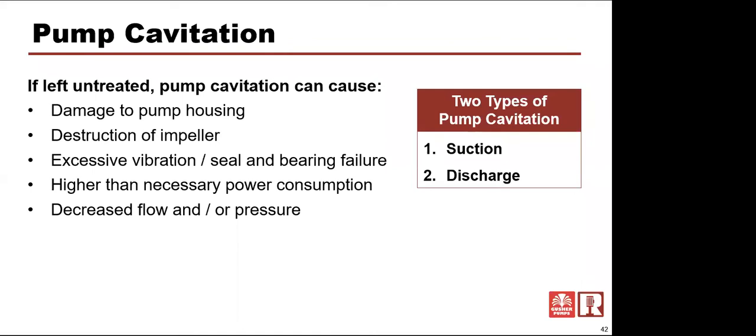It will cause premature seal and bearing failure because of all of that vibration. Again, when we get shaft movement, when we get vibration on a rotating piece of equipment, it causes us to create undue stress on bearings and the seal movement. The seals just do not like an abnormal movement at all.